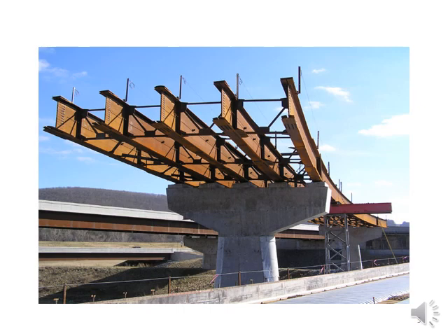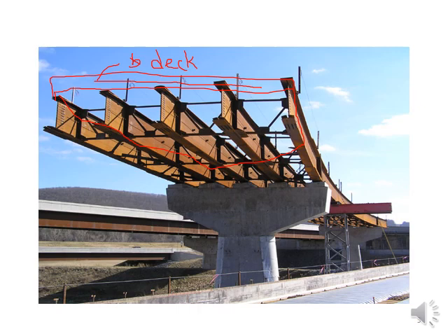Here for the steel girder bridge, the load path is that the bridge deck is missing in this particular figure. Let's suppose the bridge deck has been placed over these steel girders. Above the steel girder, first of all, you have the bridge deck. The bridge deck is responsible to carry the load at first. The moving load, all the vehicular loads and dead loads come on the bridge deck first, and from the bridge deck the load is transferred to the stringers.